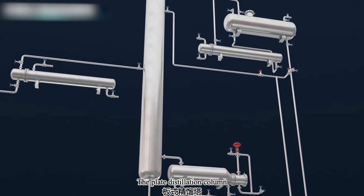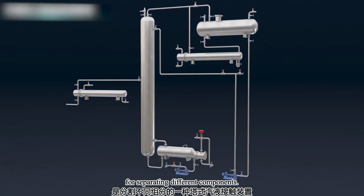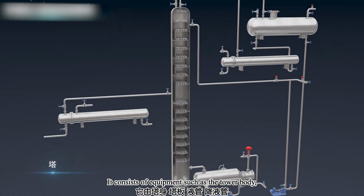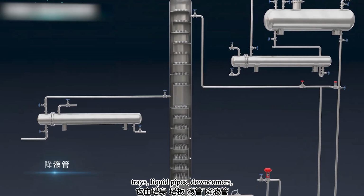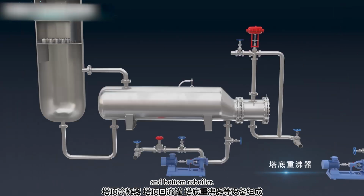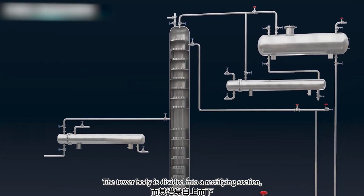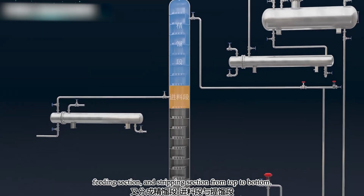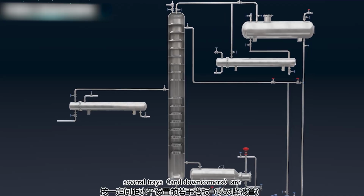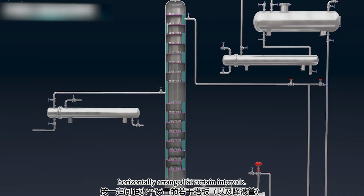The plate distillation column is a tower-type vapor-liquid contact device for separating different components. It consists of equipment such as the tower body, trays, liquid pipes, downcomers, top condenser, top reflux drum, and bottom reboiler. The tower body is divided into a rectifying section, feeding section, and stripping section from top to bottom. In the cylindrical tower body, several trays and downcomers are horizontally arranged at certain intervals.